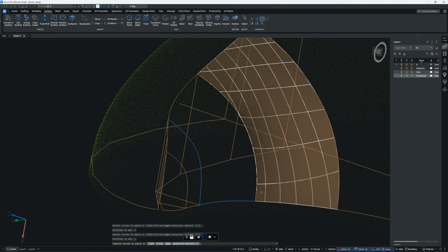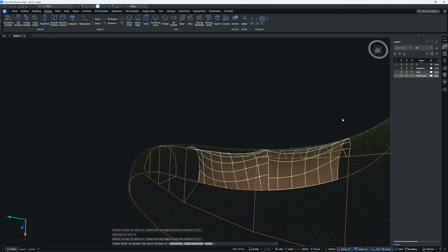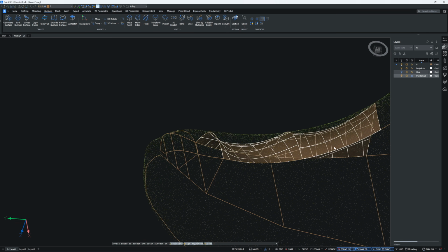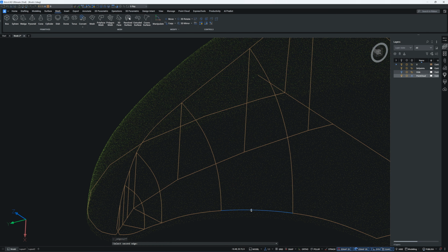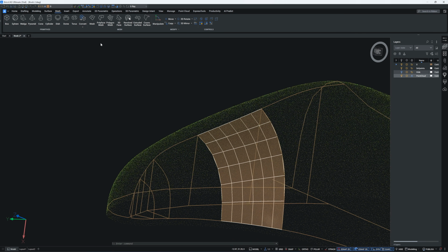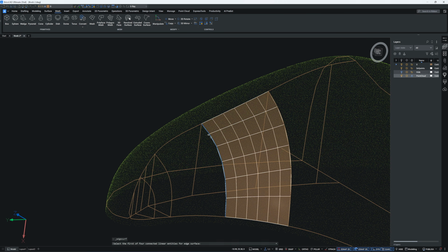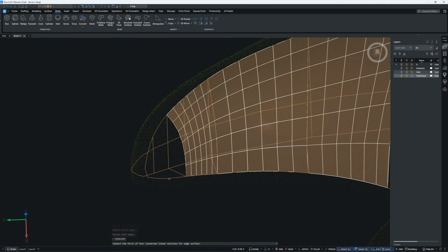The result is a concave surface, similar to when I model a tensile structure. Fortunately, BricsCAD also has a Coons surface command which produces results similar to Autodesk. To construct a Coons surface, you need 4 boundary edges, unlike a patch surface, which can be built with just 3.